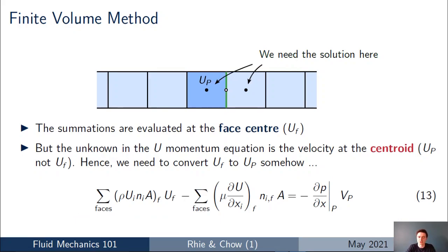And the next thing is for us to notice that in CFD codes, the majority of CFD codes, we solve and evaluate the flow quantities at the cell centroids. So when you create your mesh and you pass that to the CFD solver, and the CFD solver creates a solution for you, what you're actually doing is calculating the value of velocity and temperature, say, at the centroid of all of your cells in the mesh, and then there's a linear variation between them. But what that means for us when we set up the equations is that we need the equations to be written in terms of the flow variables at the cell centroids.